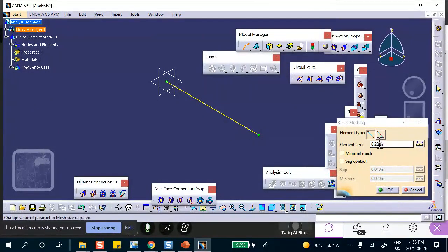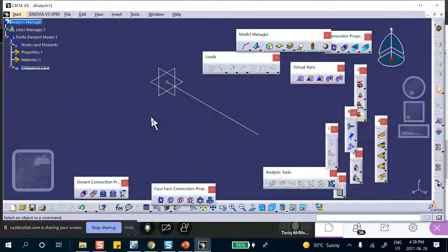Okay. I don't care about the line. Look, this was 10 inches. Remember that? This was 10 inches. Why don't I make it 10 elements? How about that? 1 inch. Remember in the other one, probably I had 2,000 elements or something like that. You know how to get the hang of these. Okay, so it meshed it.